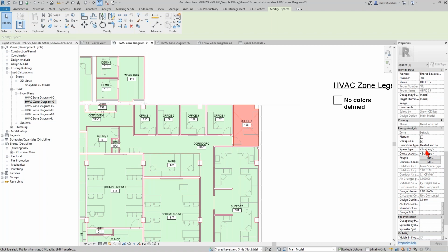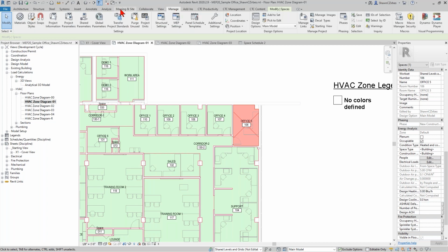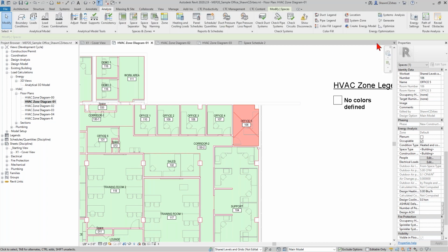Now, the building overall, in my case this model, and by default all of the models that are started from the template, unless you change it, will be set to an office type building. You can modify those from, I believe it's Analyze over here, and there's, where is it at? I forget exactly where that setting is. Not a big deal, I guess. We can come back to that later. I can also find it through here. But in the definition of the building, there are space types and building types. And in this case, by default, every space you place just leverages the default of the building.